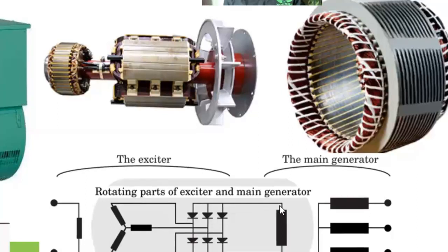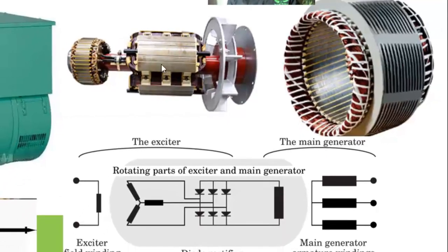So when you look at it, we have two sets of coil. This is a two-pole winding. In some cases, you have it four-pole, okay? And the pole determines the speed of the generator. So since it's a two-pole machine, it means that it is a high-speed machine, about 3,000 RPM, okay? If it is a four-pole machine, that will be running at 1,500 RPM. So let's not go into that now. You can get details of that on our training on electrical machines.